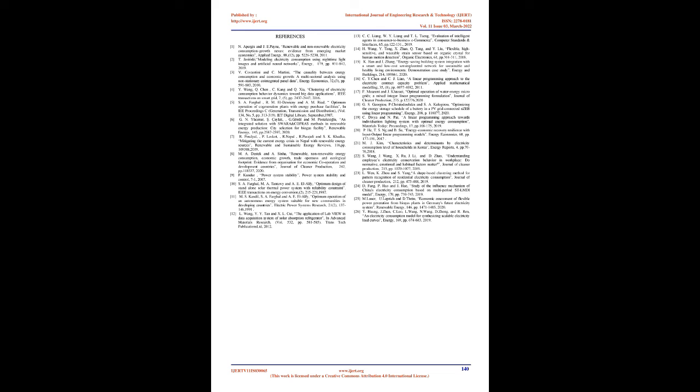Fridge. A. Leave a space of 10 to 15 centimeters behind fridges and freezers to increase ventilation for cooling tubes to reduce electricity consumption. B. Close the refrigerator tightly to reduce the leakage of cold outside or hot air into the refrigerator. C. Avoid placing the refrigerator in hot spots or in the kitchen. D. Leave hot food to cool down and then put it in the refrigerator. E. Set the temperature thermostat at 2 to 4 degrees Celsius for fridges, and about 18 to 20 degrees Celsius for freezers to reduce energy consumption.